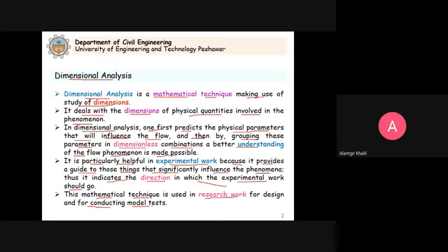So in that case, if you remember, the first thing was that you have to identify that in this specific problem, Reynolds number is important or Froude number is important, and then based on that we establish dynamic similarity and we transfer the results between the model and the prototype, or you can say that we can predict the performance of the prototype from the tests conducted on the scaled models.